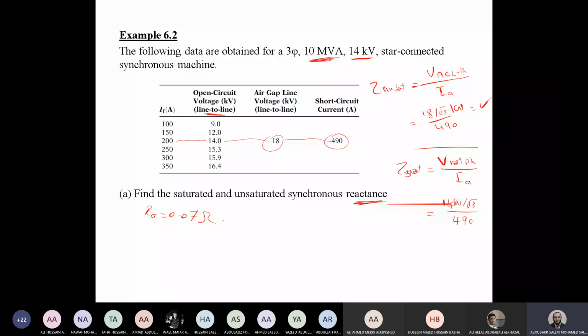Short circuit means, guys, the impedance is 0. So this means theoretically the current will be infinity. And the fuse will burn. But this is a miniature breaker, it's not a fuse. The miniature breaker will disconnect. Okay, when the miniature breaker is disconnected, is it at 20 ampere or higher than 20 ampere? Higher than 20 ampere. It should be higher because 20 is the rated value.